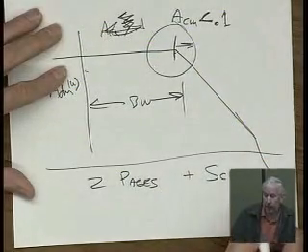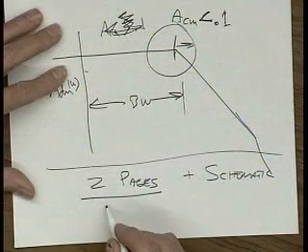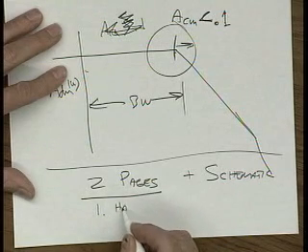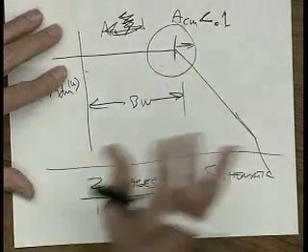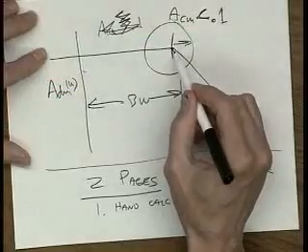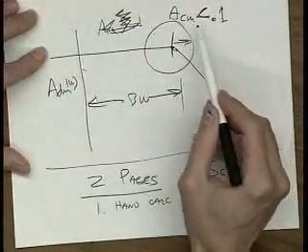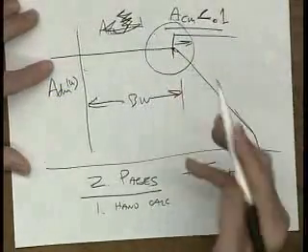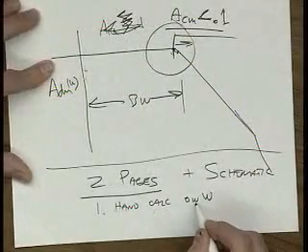In the 2 pages, the things I'm interested in are, the minimum is the hand calculation of the lowest frequency pole. You can do more in these 2 pages, but that is the minimum. And also a little bit, if the common mode gain degrades, well, it can't, right? You have to keep it up there. So hand calculation of the lowest frequency pole, omega 3 dB, okay?